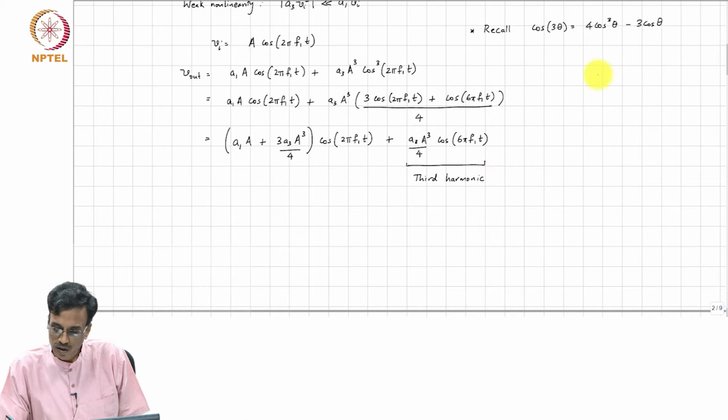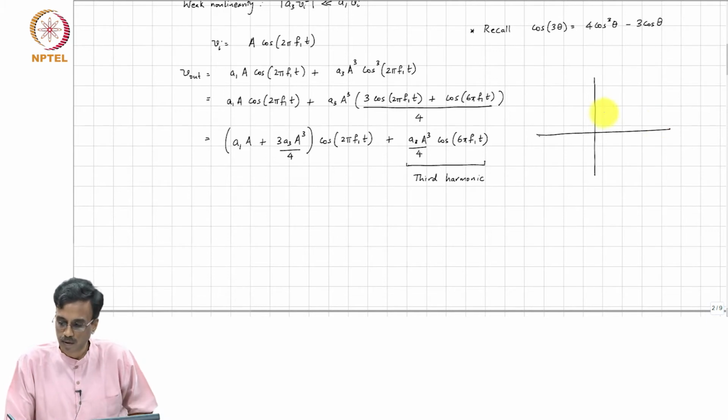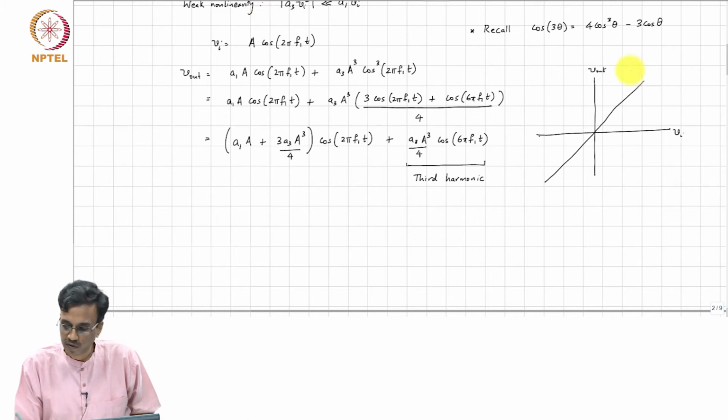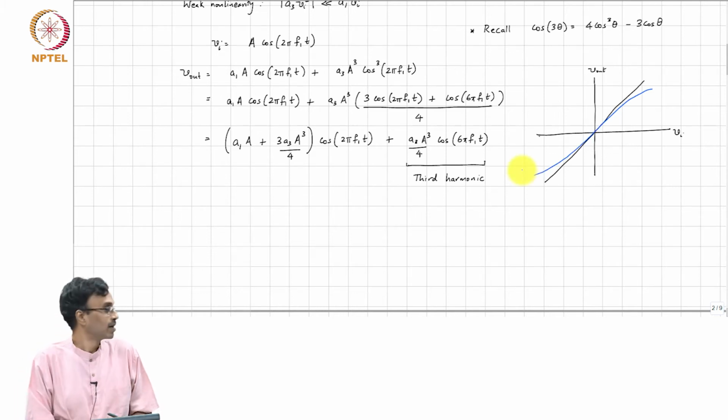And it turns out that many practical nonlinearities will have, for example, if this is perfectly linear, you would have seen a characteristic like that, right. So, this is V I and this is V out, for instance, but in practice many practical I/O transfer curves which have only odd harmonic distortion behave like that.